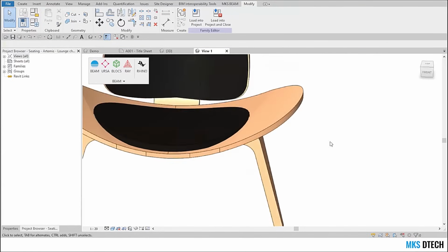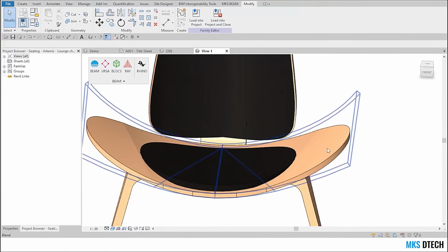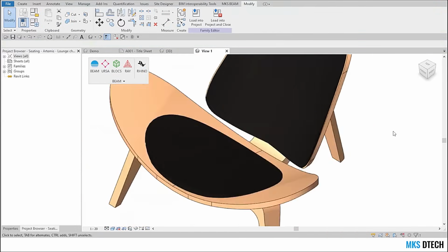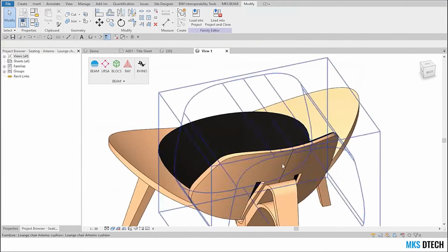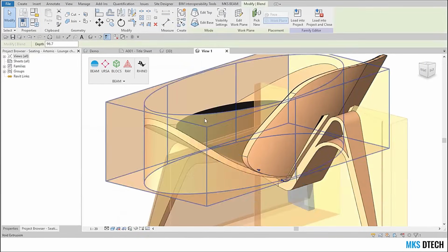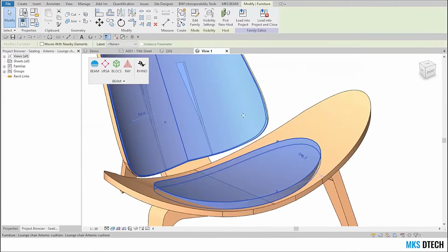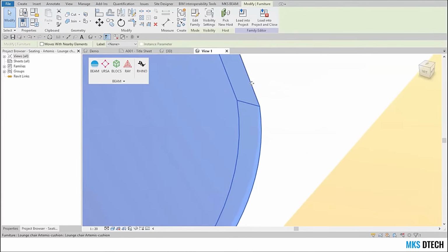So if you have this chair in Rhino, you just save it as a block somewhere, export it in a BIM folder, and you can import it and it'll be much cleaner. Look at all these operations it has to do. Sometimes you get this chair from the producer, and you can clean it up in Rhino and get it into Revit with all the materials, no problem. Because it's clear that modeling an object like this in Rhino will be much easier and much more precise.